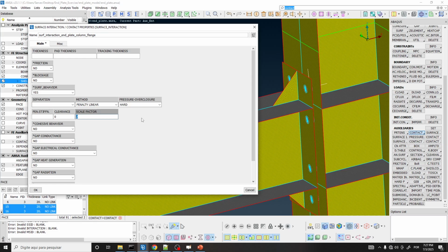So anyways, if I have a situation where there is too much penetration, I actually change the scale factor. So for example, I increase it to 1.1 or 1.2, I don't know. And then I run the analysis again and I check if the penetration is too large. And then I do this until the penetration is small enough. But I don't do this most of the time. One additional comment, this exercise is not really so much about contact. We can do later exercises where we need to work more on the contacts.